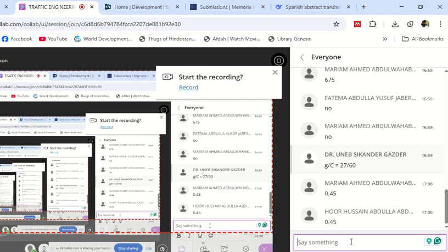Then I will achieve a flow rate which is called as saturation flow rate, because in the whole cycle the vehicles will move at minimum headway. If the whole cycle becomes effective green, then the whole cycle vehicles move at saturation flow rate. So saturation flow rate, remember, inverse of saturation headway.